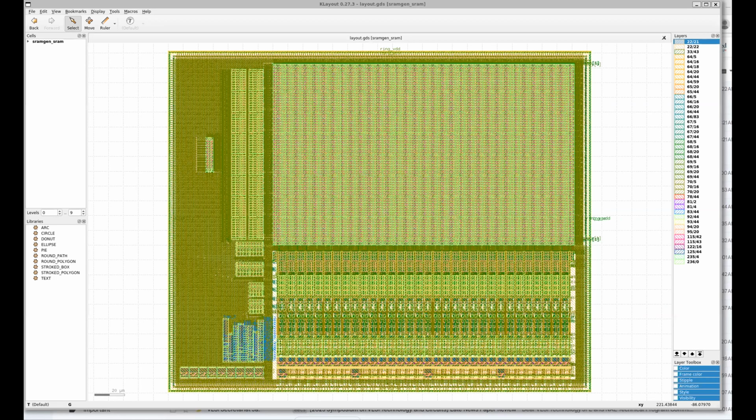Yeah, I can send you some actually good-looking SRAMs if you would like. This is a Sky130 1 KB SRAM, and the key thing there is this does have a timing replica that needs to be correct. We certainly did this with commercial tools, but you can perhaps try to correlate that with Magic and see how it looks.